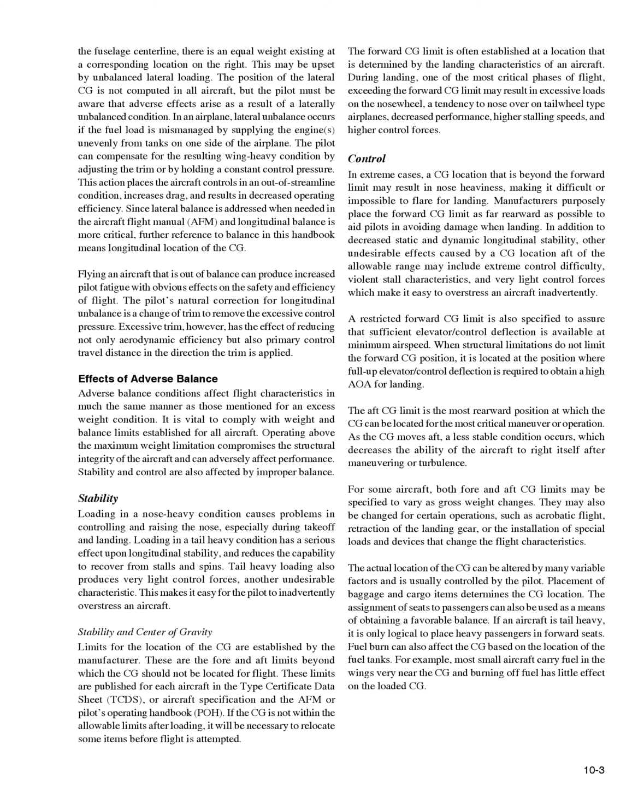In addition to decreased static and dynamic longitudinal stability, other undesirable effects caused by a CG location aft of the allowable range may include extreme control difficulty, violent stall characteristics, and very light control forces which make it easy to overstress an aircraft inadvertently. A restricted forward CG limit is also specified to assure that sufficient elevator/control deflection is available at minimum airspeed. When structural limitations do not limit the forward CG position, it is located at the position where full-up elevator/control deflection is required to obtain a high AOA for landing.